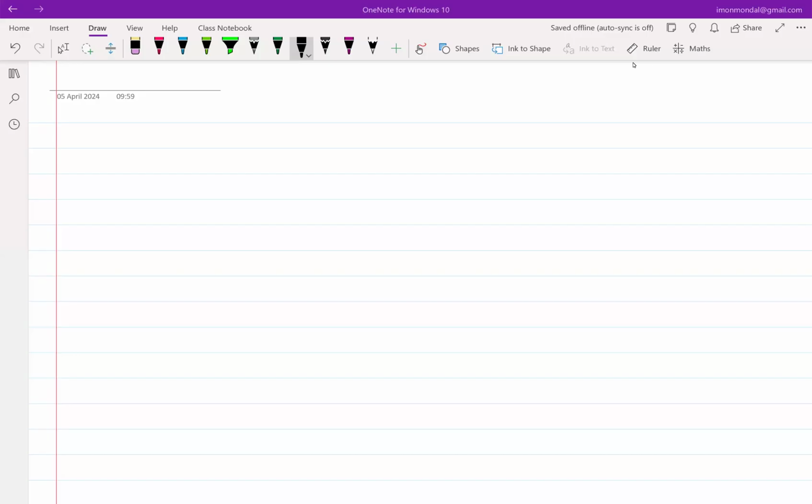So in the last class, we were discussing making an amplifier using negative feedback, an amplifier with a gain of more than one. The necessity came because in our experience till now, the only amplifier that we have which has gain of more than one is a common source amplifier. But the not so good thing about a common source amplifier is its gain is dependent on the load. So if the load changes, the gain changes.